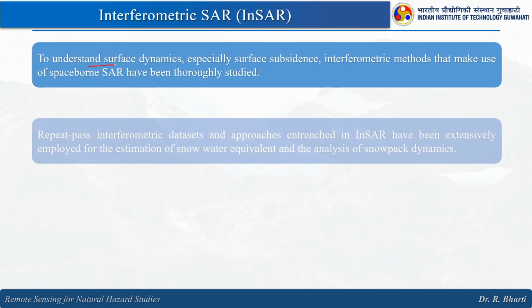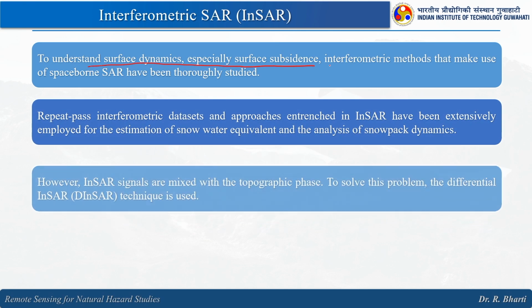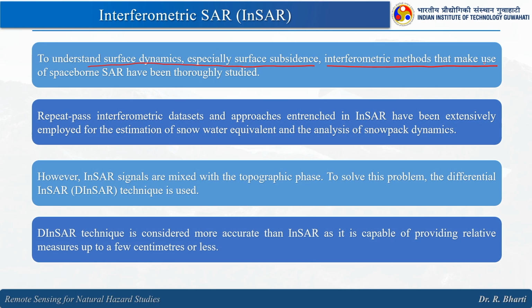To understand surface dynamics, especially surface subsidence, interferometric methods that make use of space-borne SAR have been thoroughly studied. Repeat pass interferometric datasets and approaches entrenched in InSAR have been extensively employed for the estimation of snow water equivalent and the analysis of snowpack dynamics. However, InSAR signals are mixed with the topographic phase. To solve this problem, the differential InSAR, the DInSAR technique, is used. So, today I will tell you what it is and how we are doing this, right.